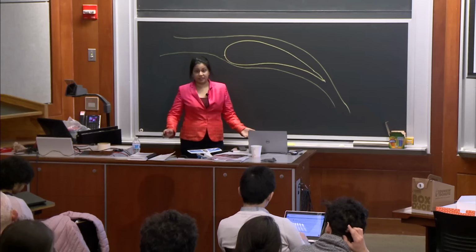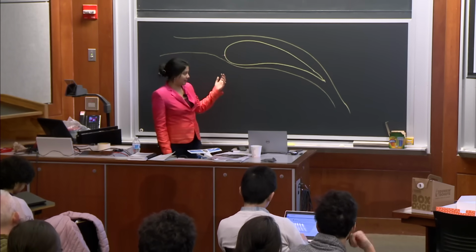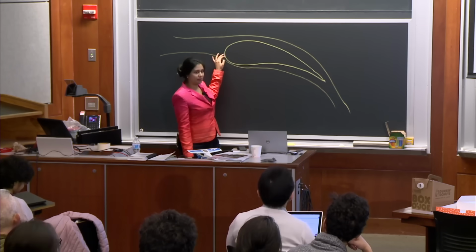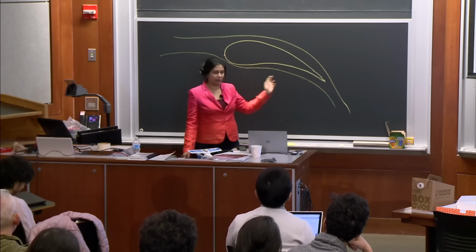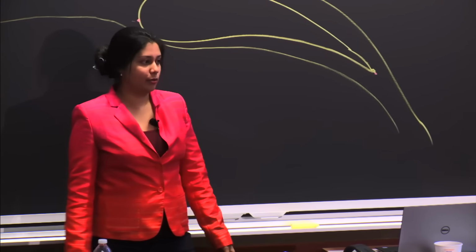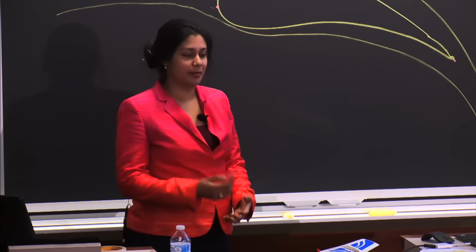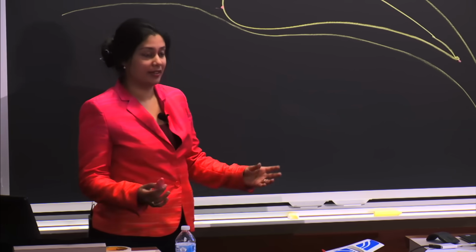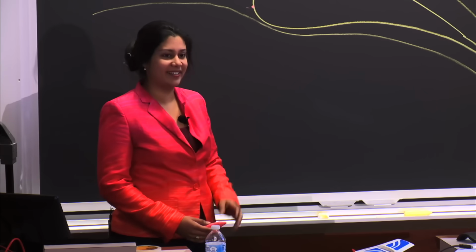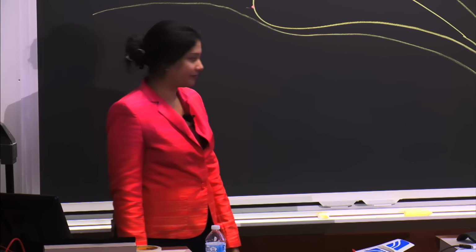So that's false, and there are many reasons why it's false. The biggest one being that there's no physical principle that says that two molecules starting at the same time, one going over the top and one going over the bottom, reaches the end at the same time. That's just not true, and we'll show you some more diagrams that show, in fact, it doesn't happen. The molecules don't reach at the same time anyway. So please, despite that being very widely propagated, that is not true, and please don't spend time on that theory.